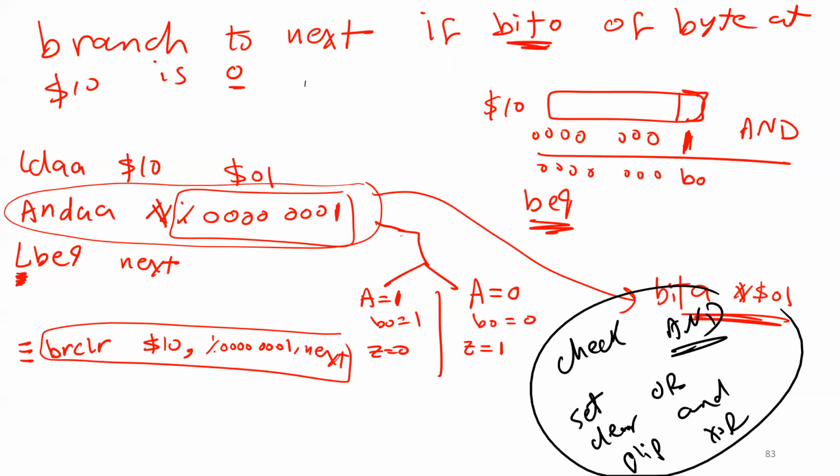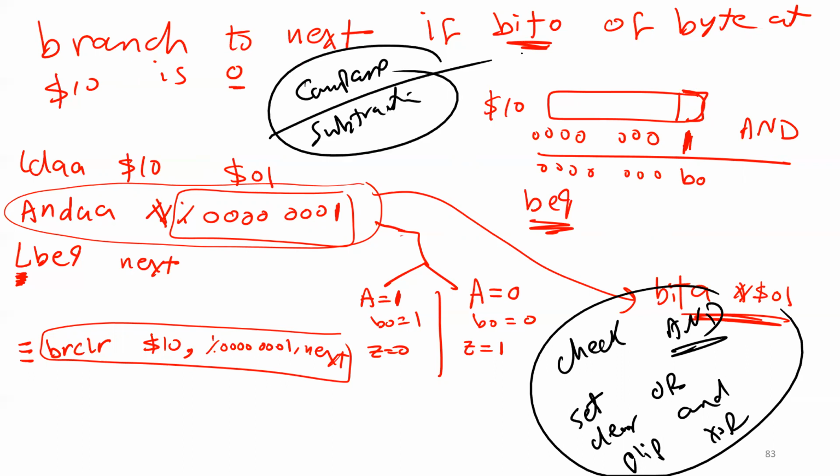Do you remember what the difference was between compare and subtraction? You remember the difference between compare and subtraction? Yes, they are exactly the same thing. Both of them are going to subtract. However, we like compare more than subtraction, because subtraction is going to change the register. It's going to store the result in the register.